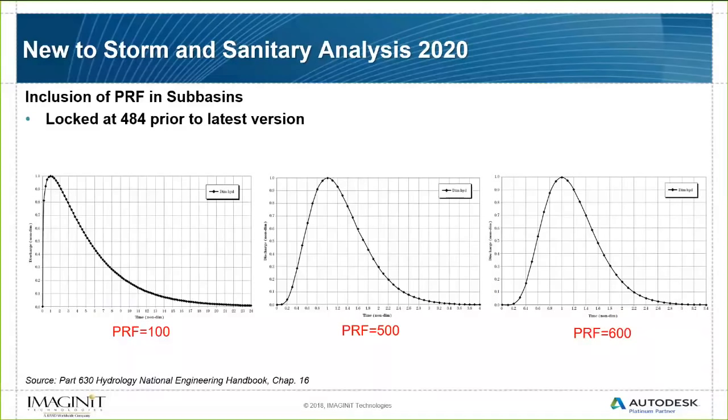yes, you can edit the grips of a catchment. But if you have to do a large change to it, sometimes it's easier to explode the catchment object so that it goes back to a polyline, and then you can use your trim commands and things like that to basically redraw it. I tend to find that's easier sometimes, so it depends on how much of a change.